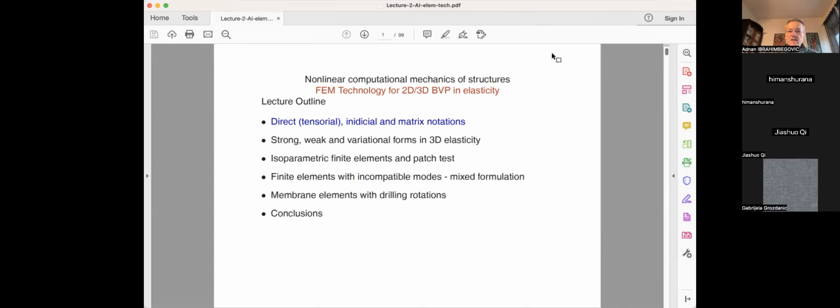In other words, to patch together compatible interpolations of, let's say, the displacement field. And then there are many more issues, such as what to use for numerical integration, and how to handle element distortion and things like that. So at the end, you realize there are many rules which are not easy to verify.